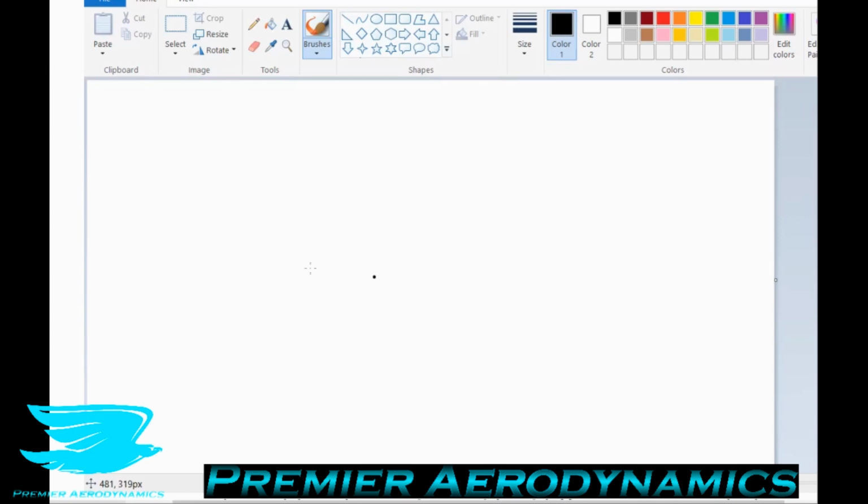So let's say we have a surface here and we have the flow going over it. Then we have at some point on the surface this little protuberance just jutting up, and it can be of any shape really, as we'll get into how these shapes do affect how well this boundary layer trip does trip the boundary layer. Anyway, the flow comes along in the boundary layer, then it hits this thing and it gets redirected up, and there's a lot of turbulence that now occurs around this trip.